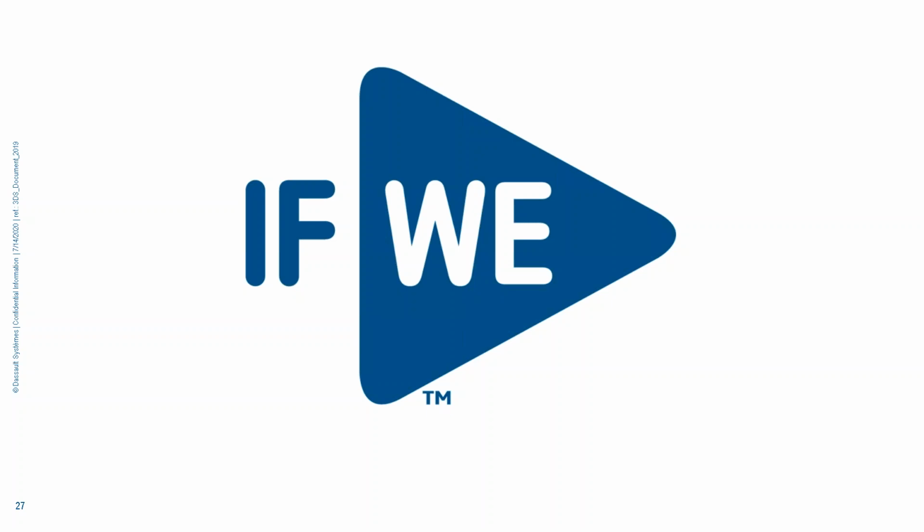But as far as a connection between a schematic symbol and its panel representation, we deal with a component. So when I place that component within that, I can have the manufacturer's part number assigned to it. The manufacturer's part number can define the schematic symbol representation and also the panel. But the software understands that once I've placed this schematic, there is a component for that schematic representation, and I just have to place the layout version of that. And as soon as I do, they're tied together associatively. So it pulls over all the tag information. It automatically knows what footprint to put in there, etc.